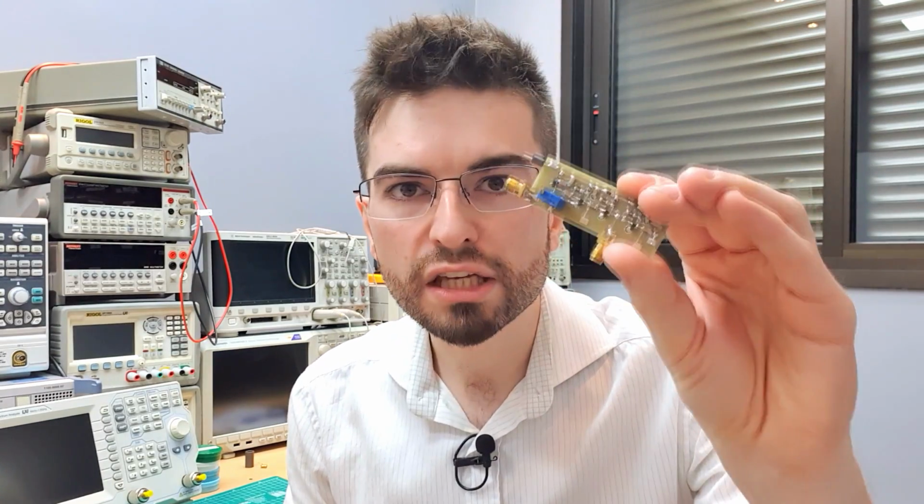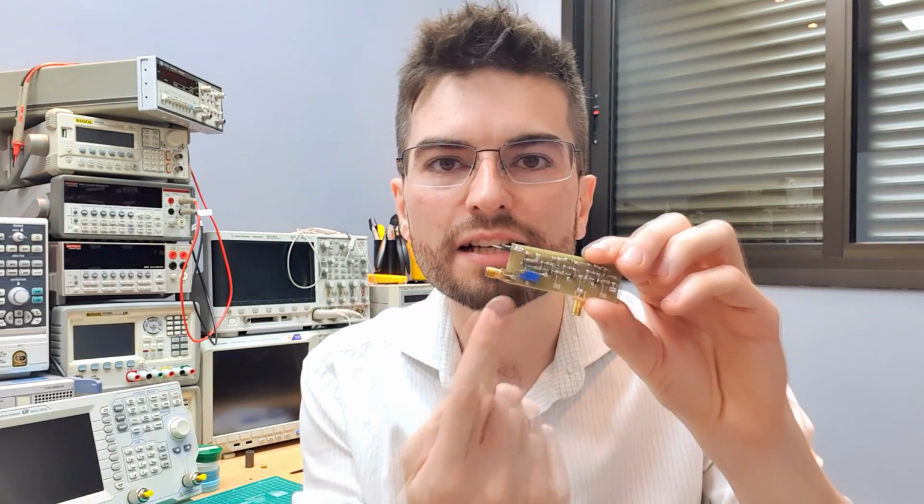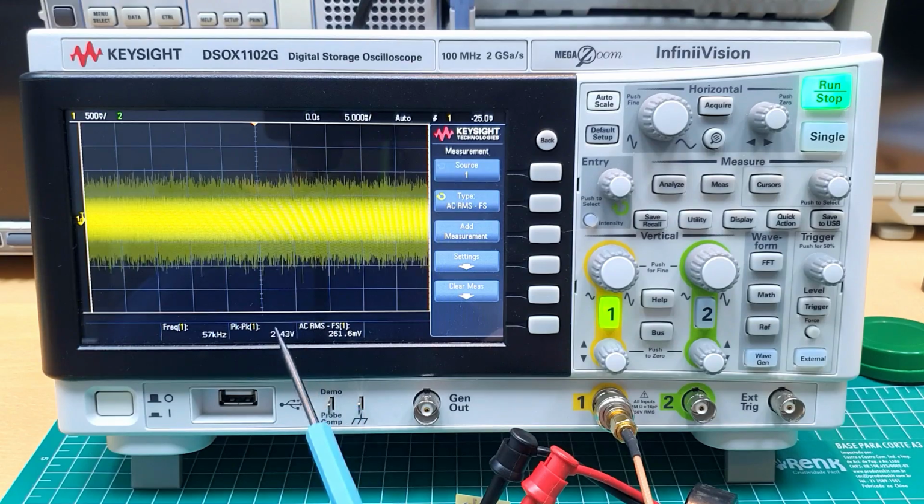When you feel that you don't understand something, go there and build. So you have the thing in your hands, you can test it, you can measure it. And this is why I constructed this with 3 stages of amplification, because I had no idea, no baseline, about the amount of noise I would get from the base-emitter junction. And with 2 amplification stages, I got exactly what I needed, 2.5 volts peak to peak.